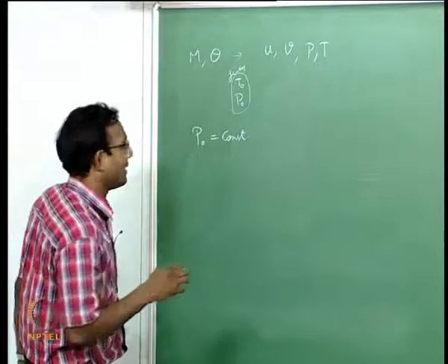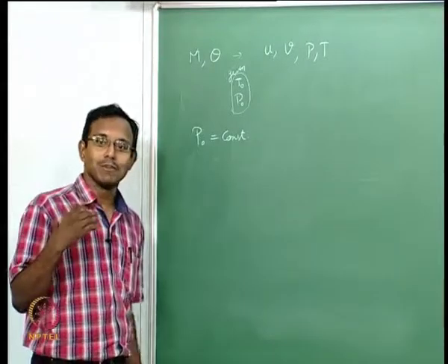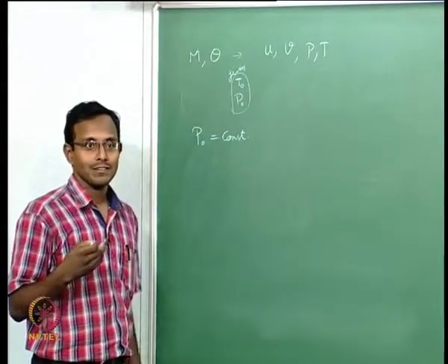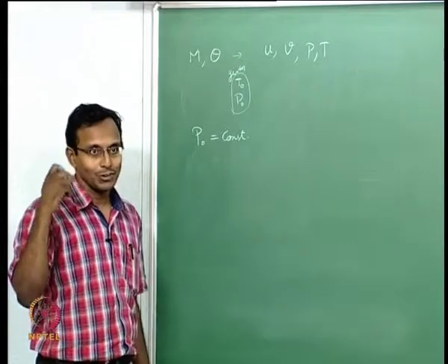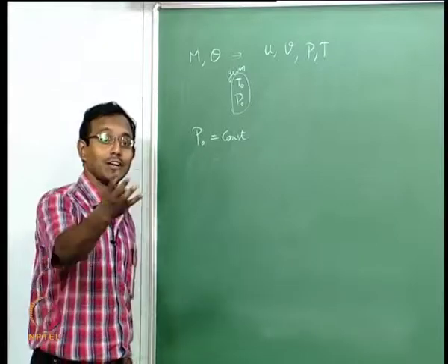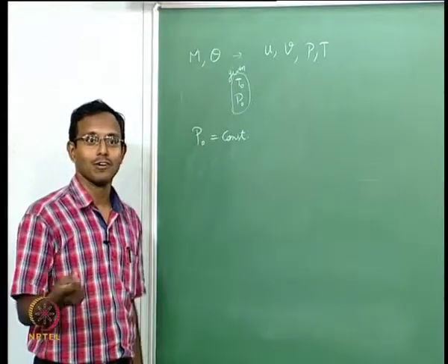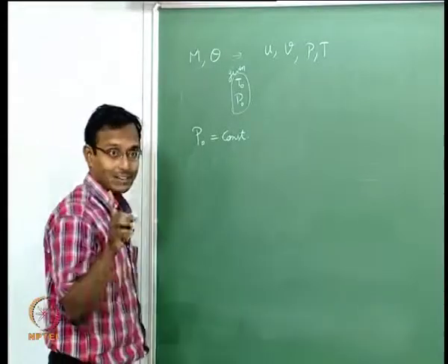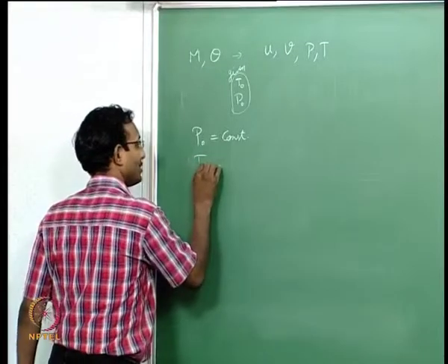And if I now say my problem is isentropic, then I can link that T02 by T01 is 1 and P02 by P01 is 1 for every point, from one point to another, always. If I say that, then I am going to say T0 is constant also.